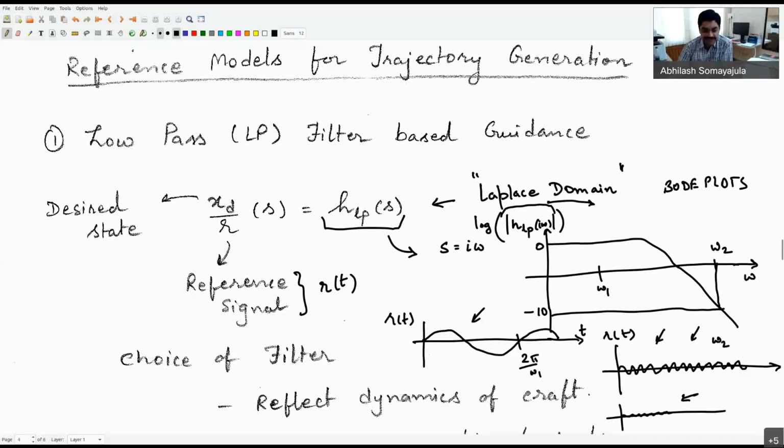So what this filter is basically saying is that anything up till this frequency, let's say omega c, which we'll call the so-called cutoff frequency, anything to the left of that, I will take it in and pass it out just as is. And anything to the right side of it, I will attenuate. So any high frequency disturbances, I'll simply reject them. Is that making sense? Yes, sir. So that's what a low pass filter is essentially doing.